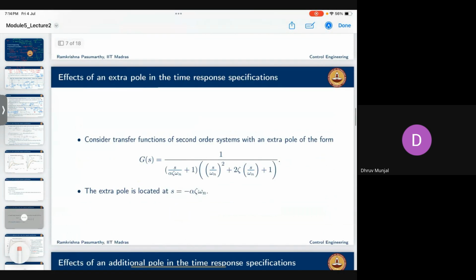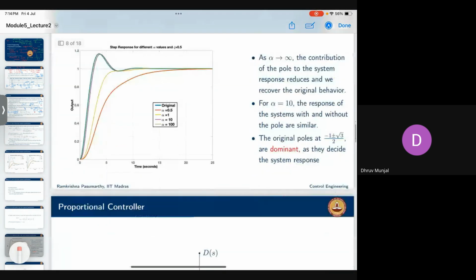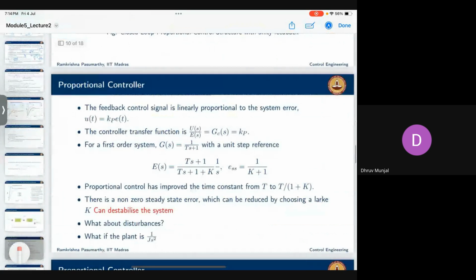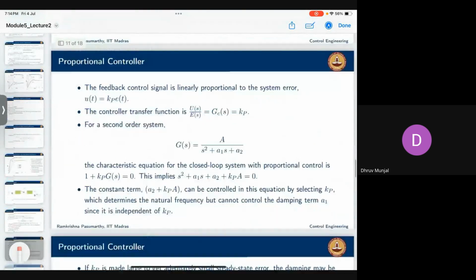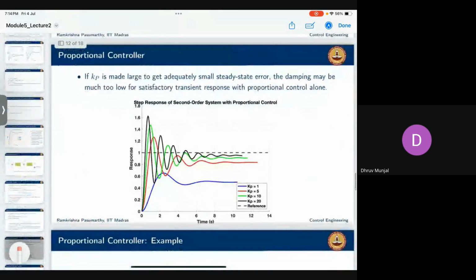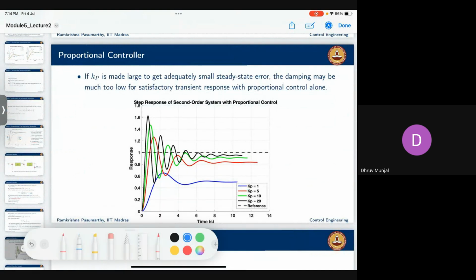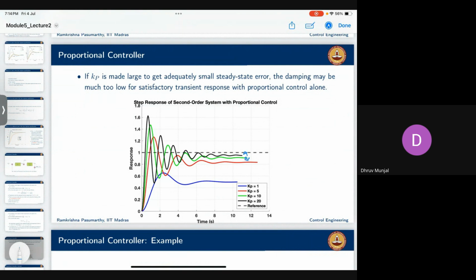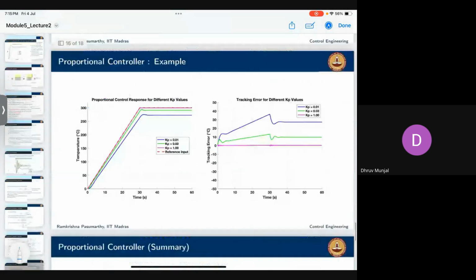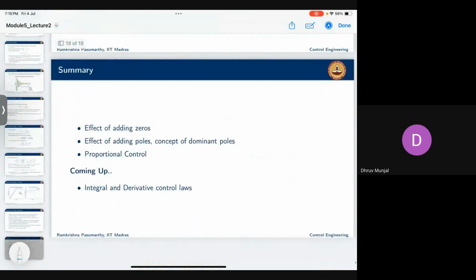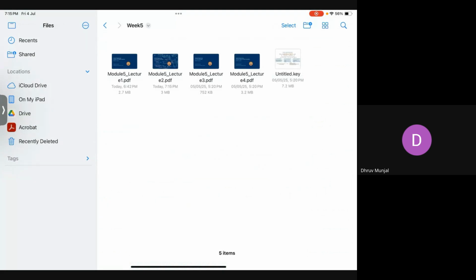Okay, then here they have explained mathematically what a proportional controller and an integral controller are. So this is what I'm saying. Here it might not go to this set point sometimes. So some constant deviation would be there, but you cannot remove it using only a proportional controller. We can solve some problems based on this, and I think it would be helpful for you.